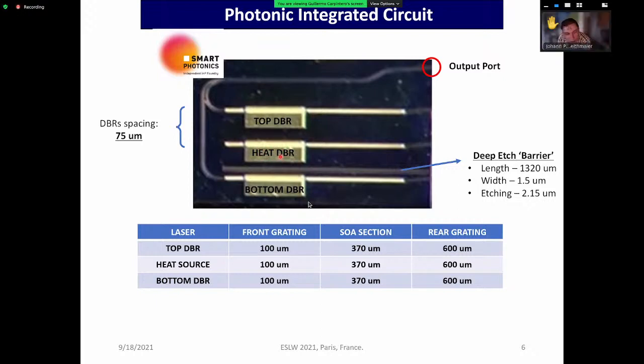Sure, but it's always a question to quantify it, because the main flow is going vertical. So even if you have a trench of 2 micron, that's only a minor blocking. And even if you cool down a certain area, I don't know if this is enough. The question is, in the end, if one has to completely redesign structures and work on vertically thermally isolated structures. But then, of course, the demand on the laser and the temperature sensitivity of the lasers is much higher. Yeah, but in this case, of course, you can then also avoid thermal crosstalk.